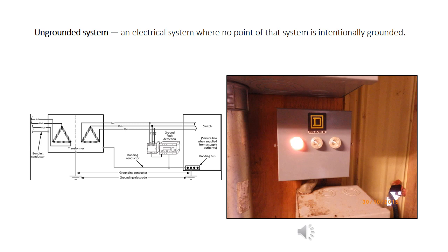Photo on the right, and no, this is not a mistake, and no, there are no burnt out lamps in this situation. Two phases have actually gone to ground. The interesting thing about this photo was that two separate businesses were connected to the utility's Delta connected transformer. Each owner had a ground fault which indicated on each other's ground fault indicating lights. That's how sensitive ground fault indicating lights actually are. They will actually detect a ground fault from a neighboring property or a neighboring customer.